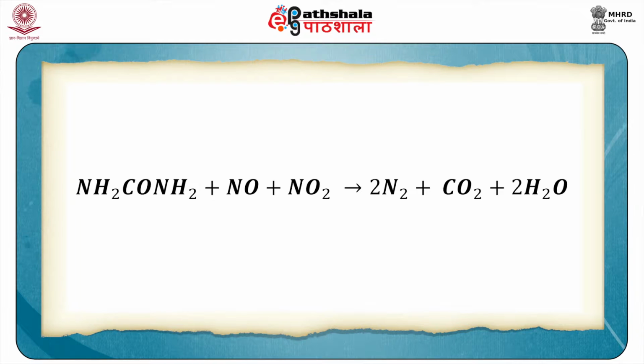It involves the injection of aqueous solution of urea in the combustion system. Urea interacts with nitrogen oxides, as a result of which carbon dioxide, nitrogen, and water are formed. It is estimated that about 80% of the nitrogen oxides are removed by NOxOut technology.